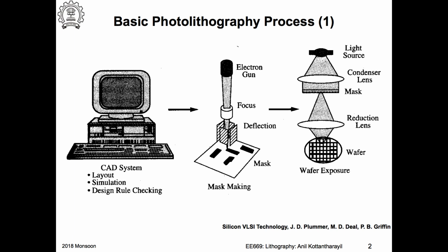Okay. So I can take this again, I would develop this wafer, or the photoresist, by dipping it in some developer. It's again some chemical solution, and I can use it further. Now you may ask this question that we actually are making a mask on the wafer. But for that we may have already made a mask here.